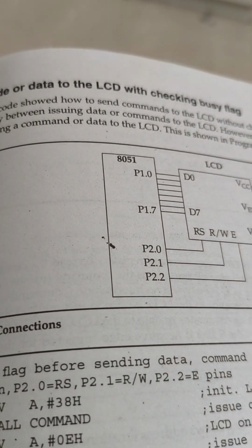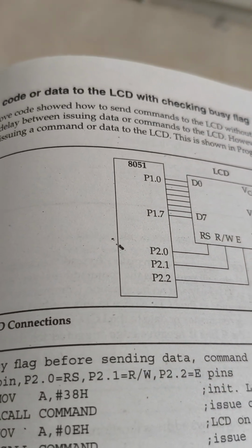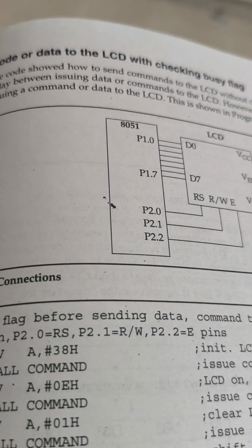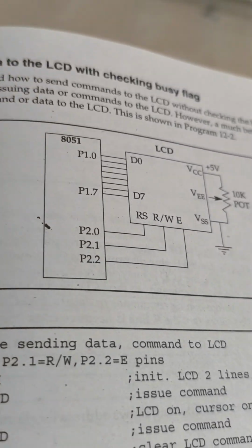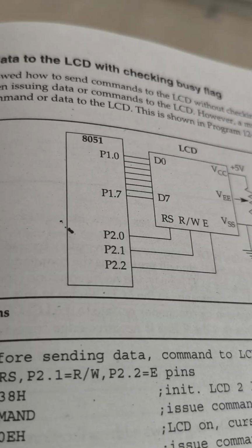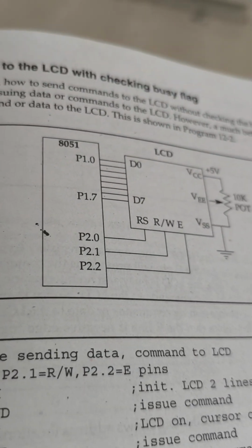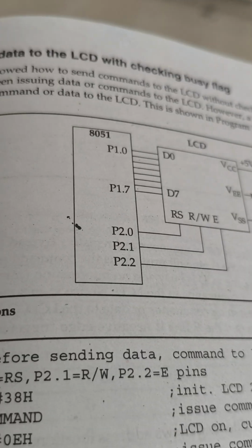Here, from pin P1.0 to P1.7, it is a total of 8 bits, an 8-bit data bus, which we give to D0 to D7.